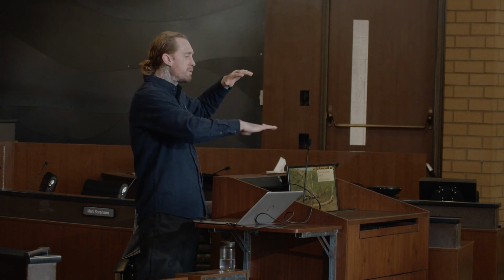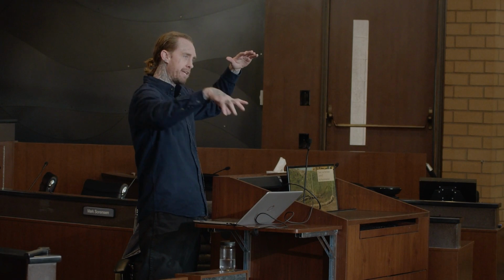Think of a new development where they've graded out the streets. Usually the pads are a little bit higher and they grade out the street. Well, what usually happens during a rainstorm is that the rain will erode the material on the pad and it will run into the graded street area, right? So it'll create erosion on the pad and it will bring sediment down into where the street is going to be, where all the lifts will be taking place. Not only have you degraded your pad, the slope of the pad, but now you've added sediment into a pre-graded area, which you're going to have to get graders to come back out and regrade.